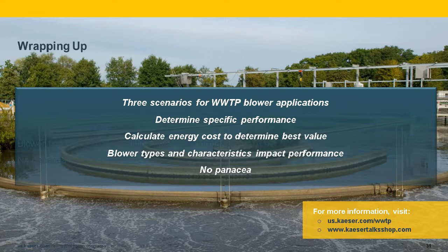So with an ISO 1217, you are measuring the output flow of the machine at the discharge of the unit, and you are measuring the input kilowatt. So by measuring the output flow and measuring the total package input, you're getting the delivered flow and measuring all the power. So this would be your wire-to-air for certain, which includes measured losses through the machine. But ISO 1217 refers us to a specific performance. Gotcha, okay.